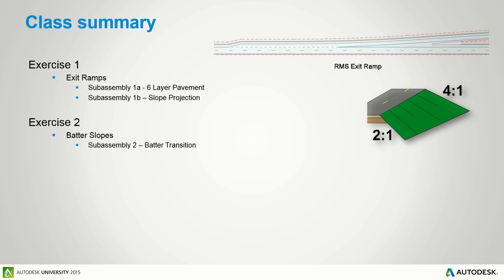Exercise 2, we're going to build upon what we learned in exercise 1. We're going to look at the concept of transitioning across our regions in Civil 3D. Now, when I first moved to Civil 3D, I found this really difficult to do, getting that whole concept of data transitions. We're also going to look at the concept of linked corridors, so we can actually break our model up into much more manageable components, but still keeping the corridors linked in the event of change.